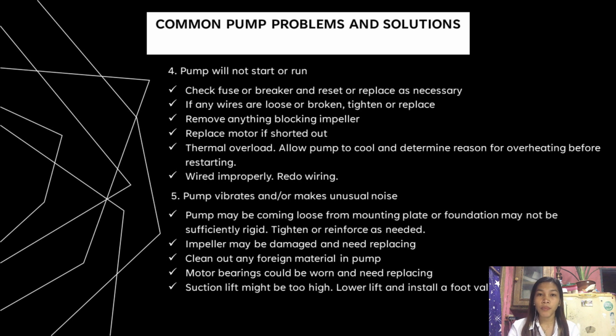Next problem is pump will not start or run. The solution for this is first, check fuse or breaker and reset or replace as necessary. If any wires are loose or broken, tighten or replace. Remove anything blocking impeller. Replace motor if shorted out. Thermal overload: allow pump to cool and determine reason for overheating before restarting. Wired improperly: redo wiring. Fifth common pump problem is pump vibrates or makes unusual noise.